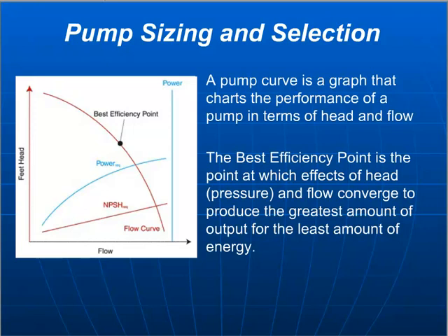So pump sizing and selection, the main thing here is just, you're going to have a certain flow rate and you're going to have some elevation, some head requirement of your pump. And once you know those two things, you're just going to have to look at what's available locally, and you're going to probably be dealing with a small subset of total pump options out there, especially if electricity is not an option.